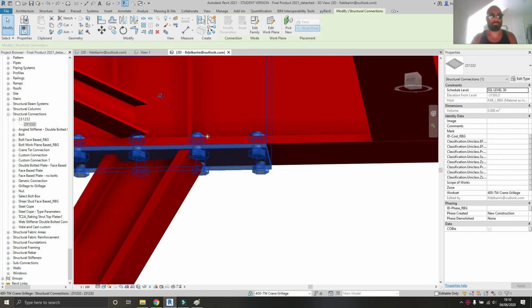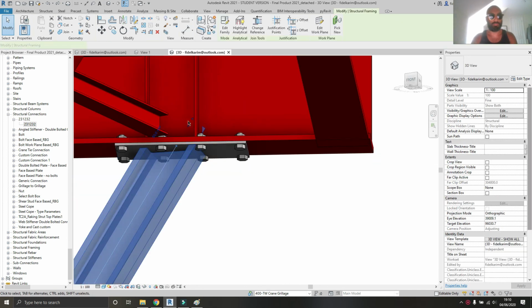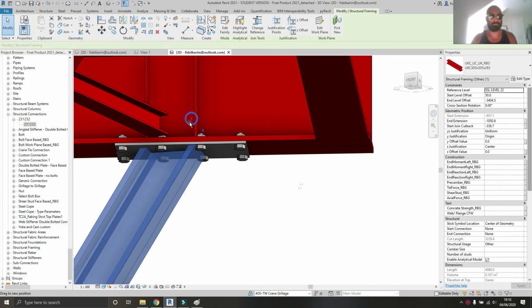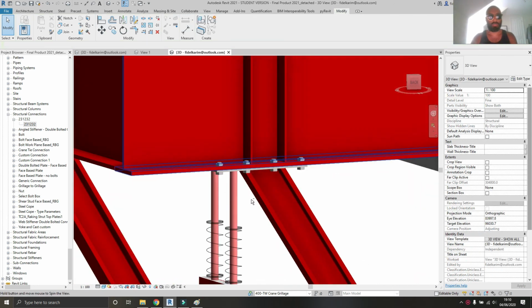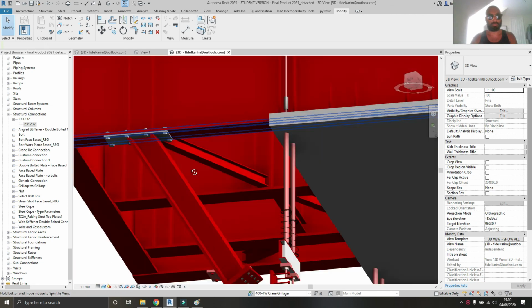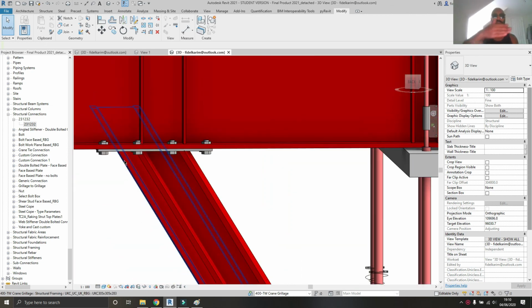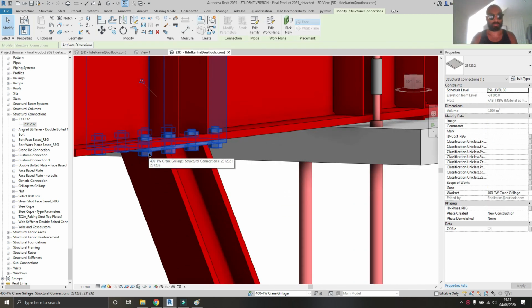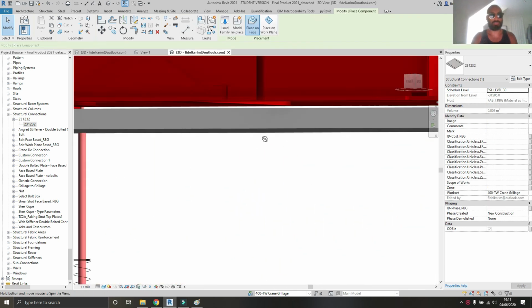You can expand it a little bit. The cut, that is. Yeah, the void inside the model. For this case, it's fine like that. And there you go. That's a very nice little structural connection. You can position this one a bit better if you like. And if I want to create that again, select it, type CS.